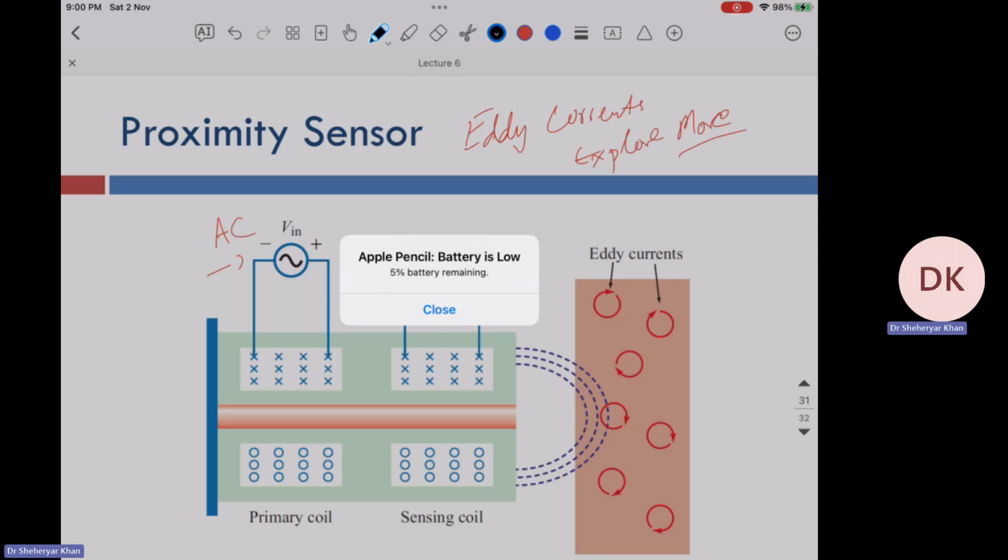So it's not a complete conductor. We have very small conductors, and then we put them into the lamination such that we do have magnetic flux, but we break the path of the current. So I squared R losses are minimized. Right. So we use simple disc laminations. There are many ways.